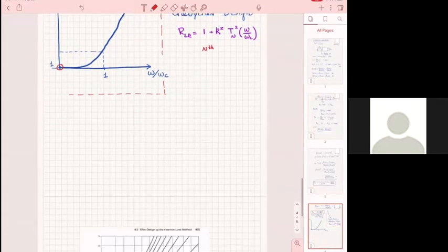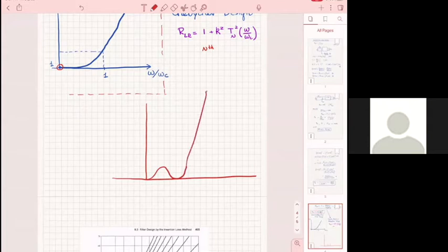All right. Now, as I said, the Chebyshev polynomials have two interesting properties. They are both oscillatory in form and also monotonic. And so this was selected. So instead of going flat, the filter will do this oscillation and then go up. Now, this is where omega over omega c equals 1. And this is the 1 plus k squared.